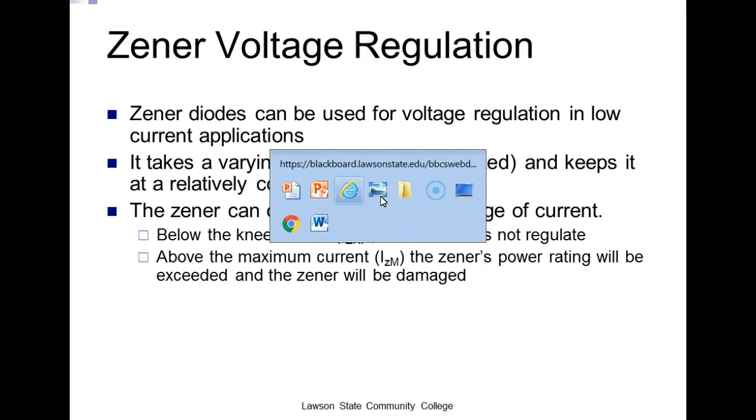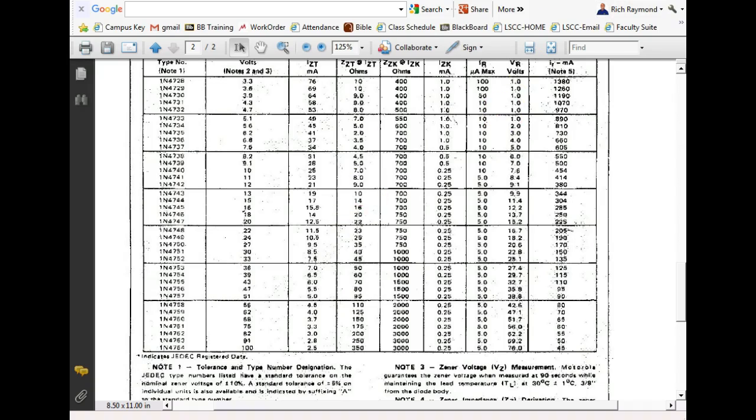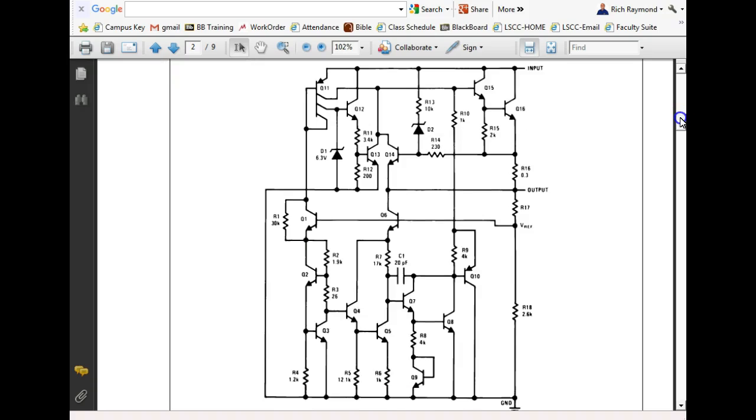And that's what just about all your voltage regulators do. So if we look at a 78, this is a 7800 series, and it's got all these bipolar transistors in here we'll talk about, but sitting right here in the heart of it is what? Zener diodes. So we're using the Zeners for the reference for the 5 volts, or the reference for the 12 volts, and then we're supporting it with all these other electronic devices, not only to increase the current, but also add current limiting and over voltage protection and all the other kind of stuff.